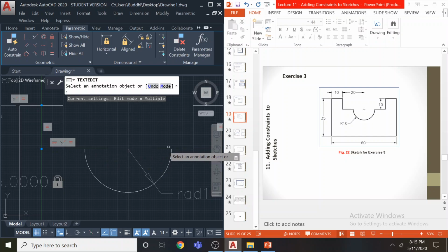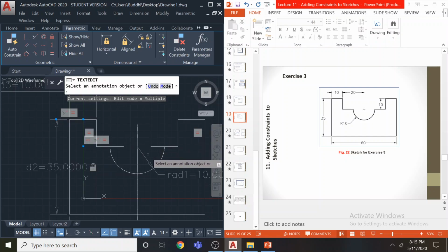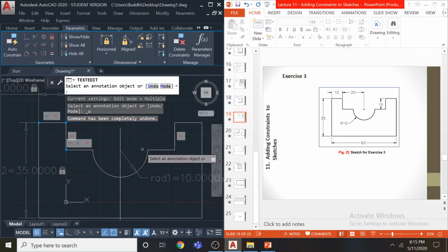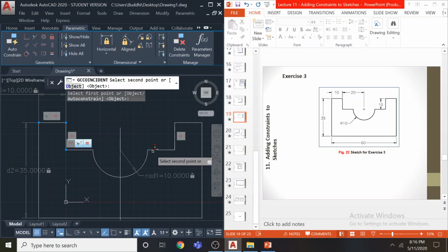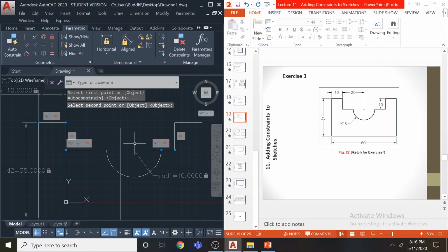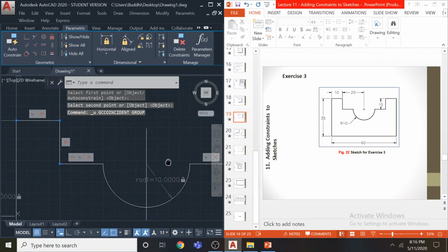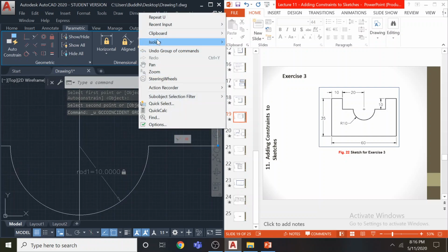See, I didn't give any coincident relations. So before you finalize the drawing, make sure every joint is connected using the coincident symbols. So I will apply the coincident symbol relation here. Done. So you see it's now there's a problem. So I will apply again.